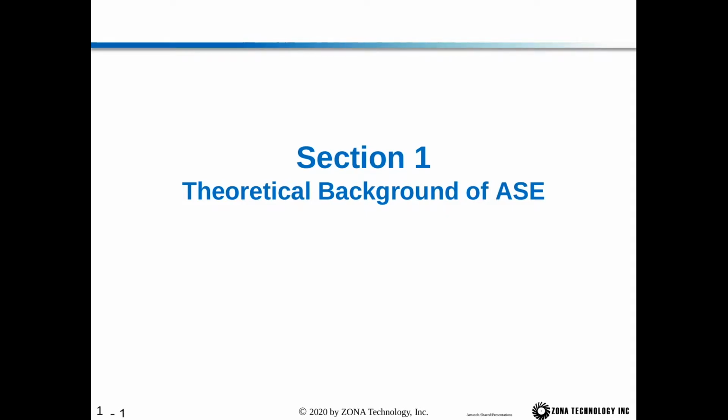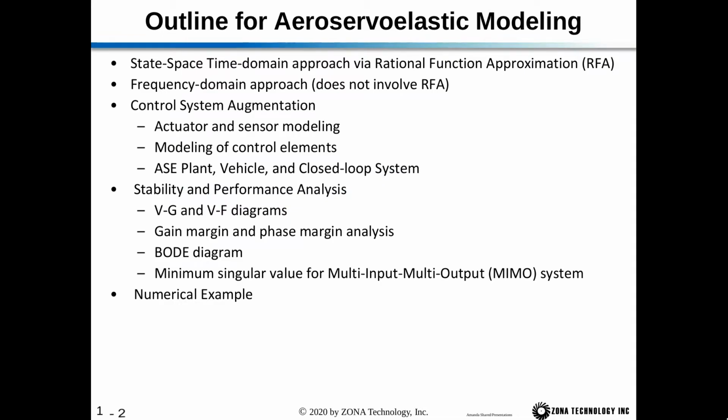Section 1 of the ZAERO Advanced Training: Theoretical Background of ASE. So the outline here for the aero-servo-elastic modeling in ZAERO: we have a state space time domain approach via the rational function approximation. We have a frequency domain approach which does not involve the rational function approximation. We have control system augmentation, which allows for actuator and sensor modeling, the modeling of control elements, and then you can output the ASE plant, vehicle, and closed loop system plant models.